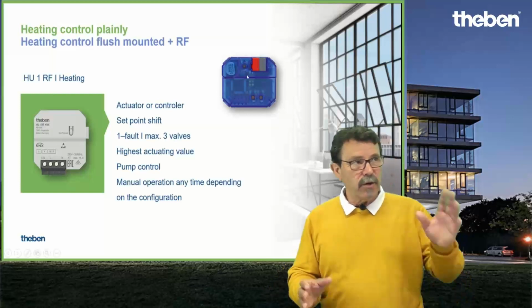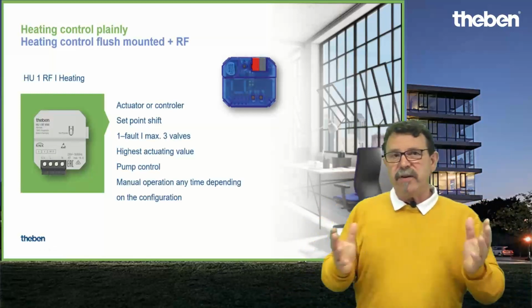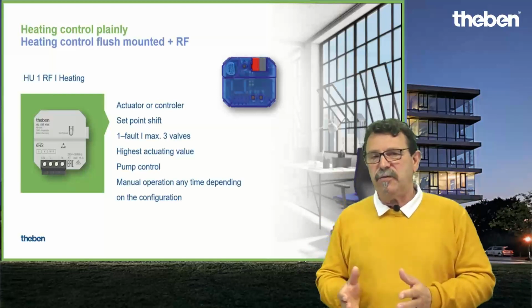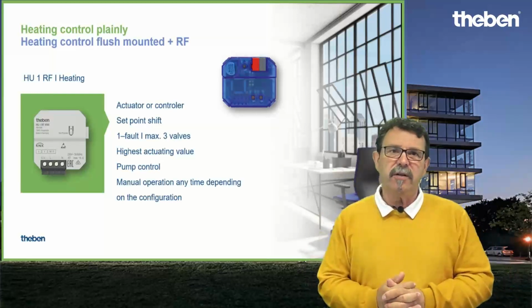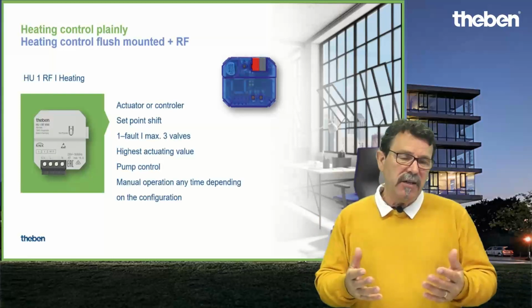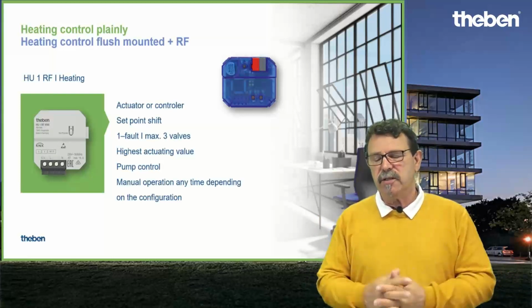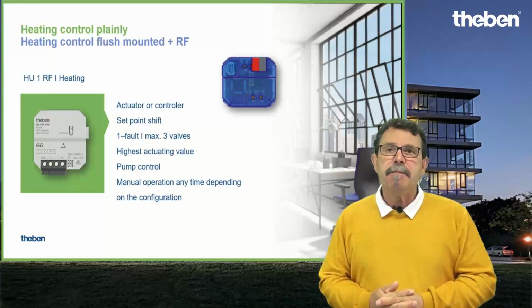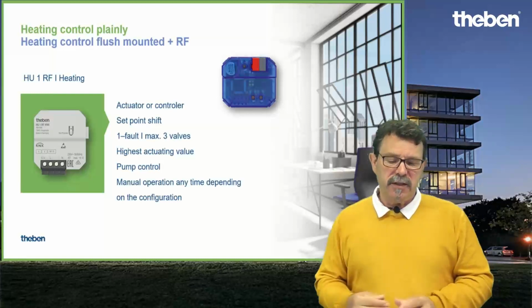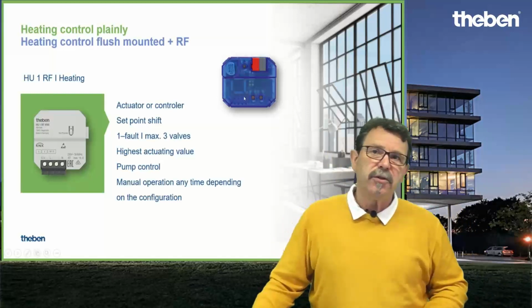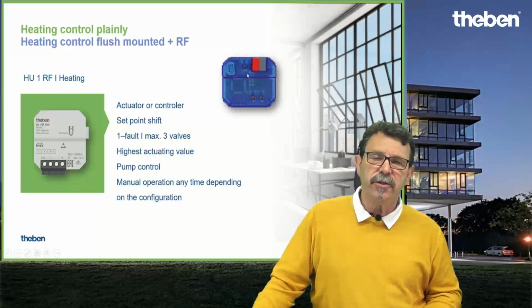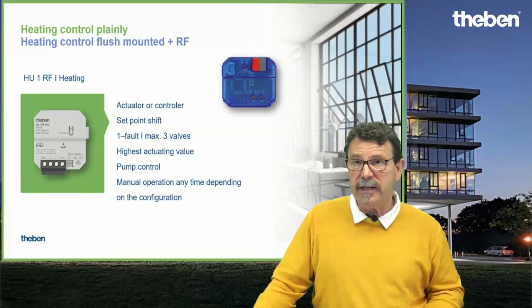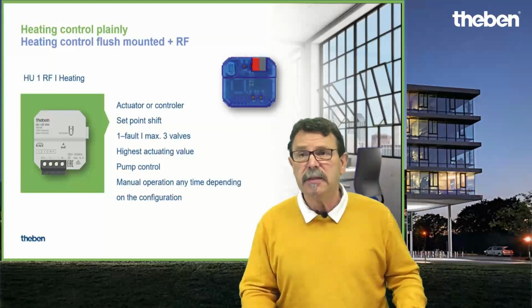I come closely to the end now. In some events you might not have the cabling to do an extension in the building, but you still need the heating solution. What you can do in such a project is use a kind of media coupler, which talks RF secure. This has to be linked, hardwired to the KNX bus system, sure.